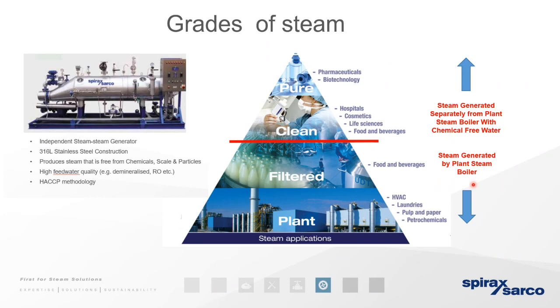So again, once steam becomes an ingredient of your process, then we need to start moving to clean steam. Yes, steam is sterile, absolutely. It is clean when it's produced. But in most cases, if I had to come to your site and ask you to drink your condensate, you will most likely tell me that I'm mad. Yes, because that is not clean. It is sterile, yes, it has been produced in a boiler, but when it comes to consumers, as soon as it becomes an ingredient, the steam grade changes dramatically.